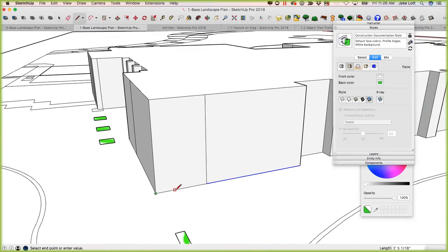The way SketchUp works, again, is this line is a solid stitched together line. But if I were to draw a line and intersect it, it automatically cuts it into two lines. So we could start drawing a line even along itself and type in, we'd have to figure out that total length there, and maybe we want to divide it into even sections.